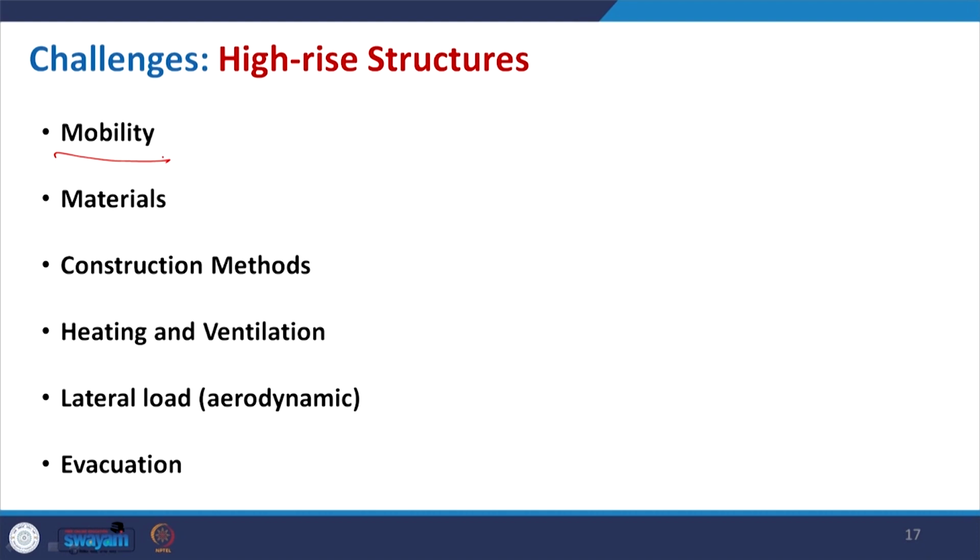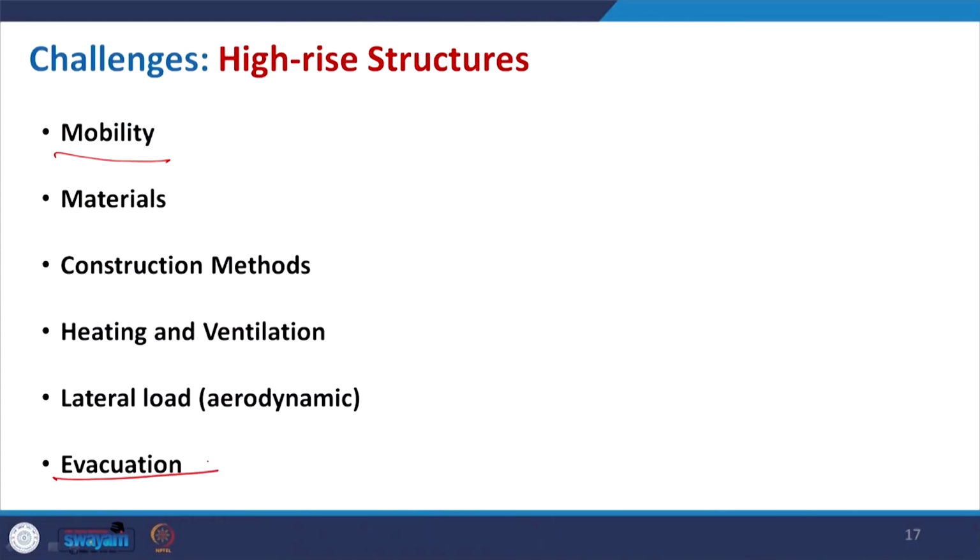It is not only the movement of the people, but when you build it, it also requires some kind of system. So, for high rise this is very important, and also we should think of the evacuation. For that you have to think of high level services in terms of lift, high speed lift, so that within a given time of evacuation, whatever the standard time, within that the people from inside they can come outside.